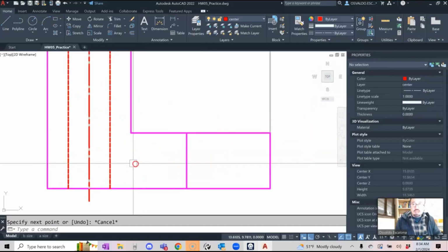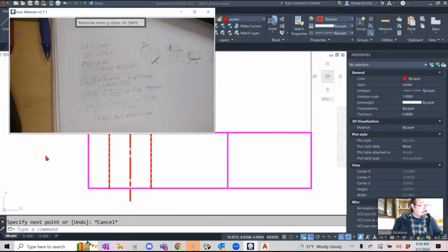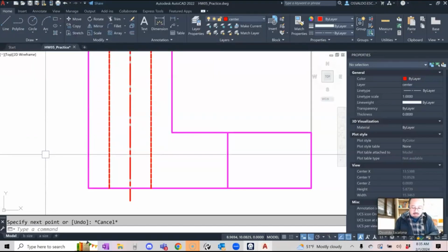Okay. If you believe that your center lines are too close, maybe you can also change that spacing. The command for that is line type scale. So again, this is a command. The next command is LTS, line type scale. Let's call this the line space. It will just go and separate these dashes. So the regular will go LTS, line type scale.